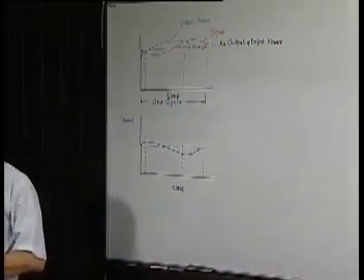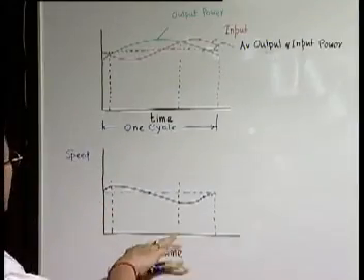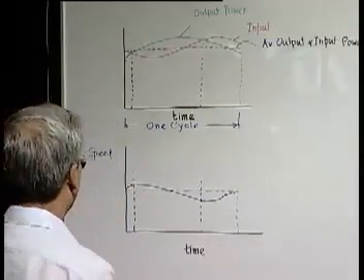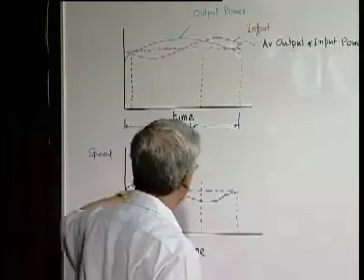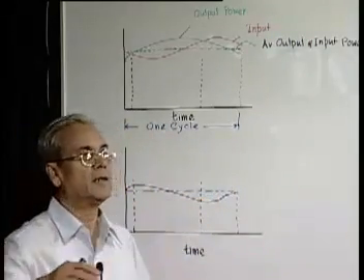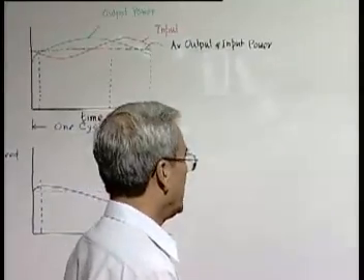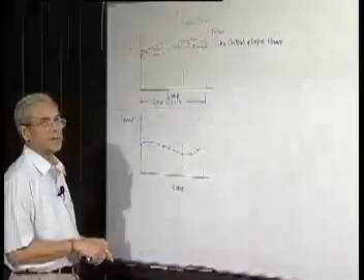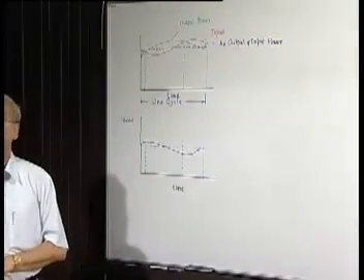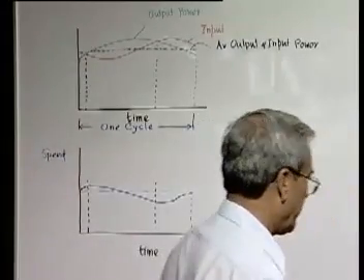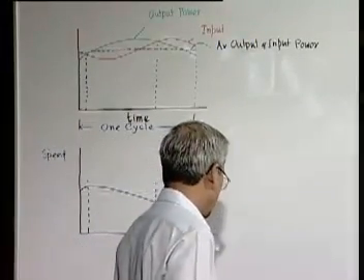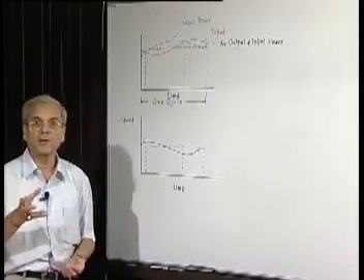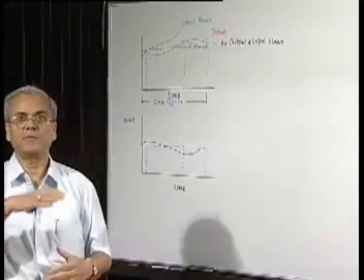Therefore, you can see that in general, where the output power and input power instantaneous values do not match at every instant, but the averages are same, though the average speed will remain constant, the instantaneous value of the running speed of the system will change or fluctuate, and there is a cycle after which the whole thing will repeat. This is in general the situation with all cases. So, therefore, we now have a non-steady or rather non-smooth operation. The operating speed of the system is fluctuating.